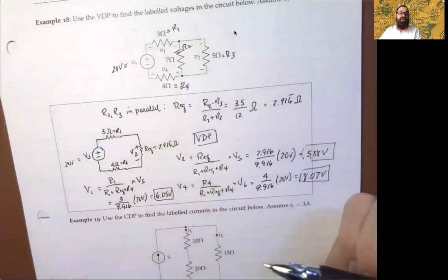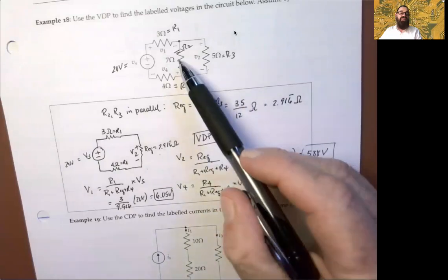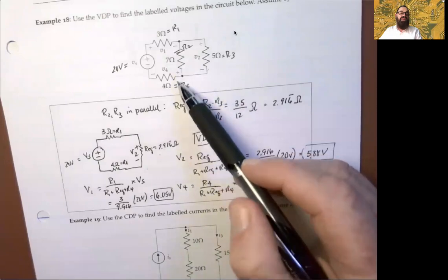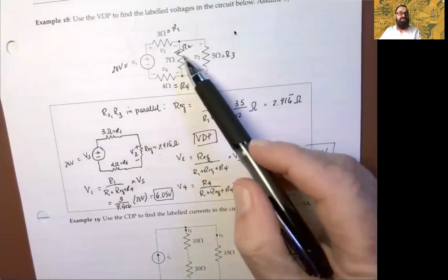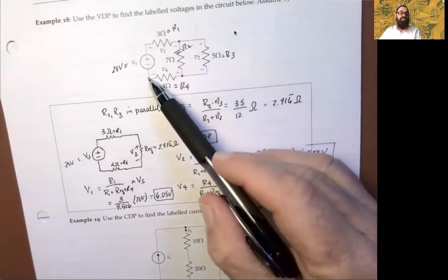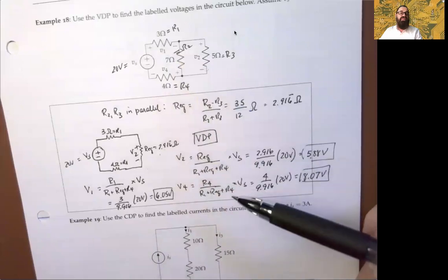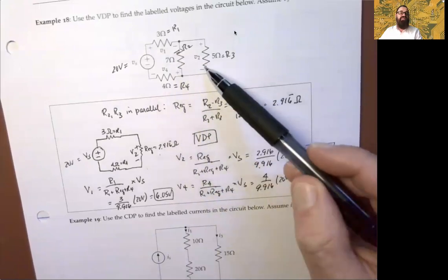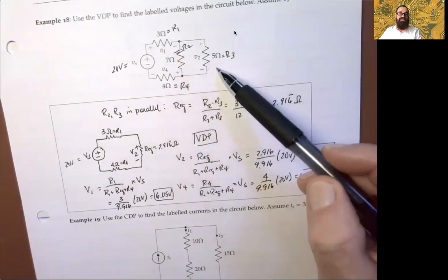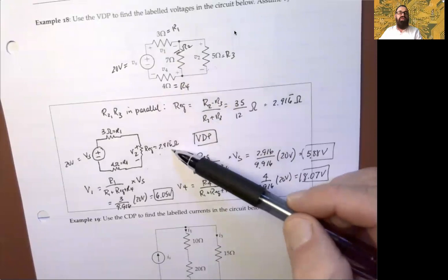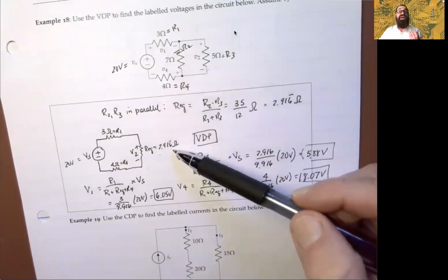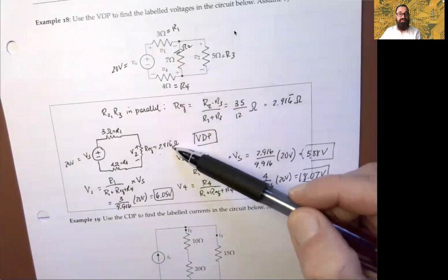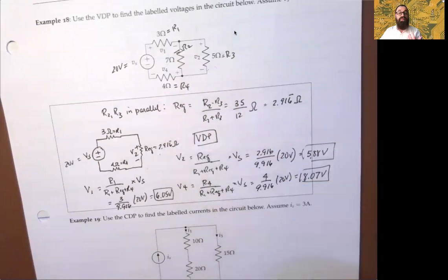So it's interesting that even though this is a larger ohm than that, this parallelism is causing you to get the same voltage to occur there, right? And the fraction was based on the equivalent resistance, which is less than the 5 and the 7. See, it's less than the 7 and the 5. It's interesting, because when they're parallel, you will drop the equivalent in terms of the resistance. If they're in series, you're going to add them. It's going to get bigger, but it drops when they're in parallel, okay? So your voltage will go up. Interesting. So let's continue on.